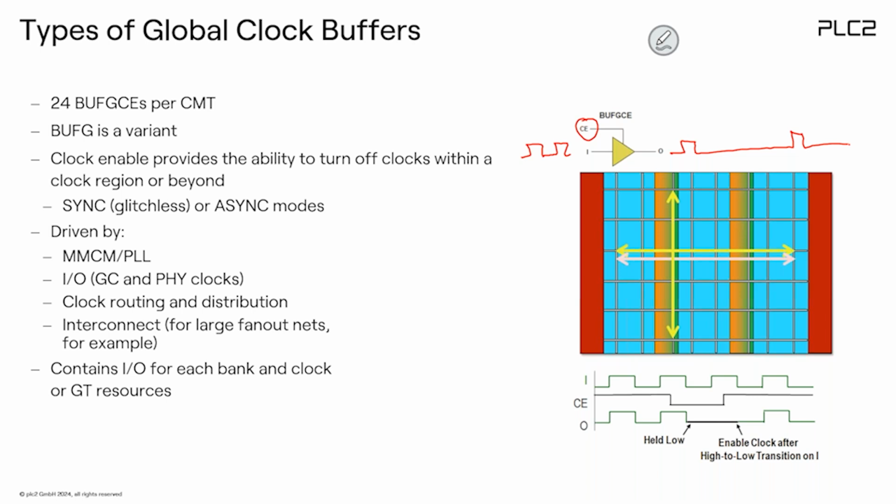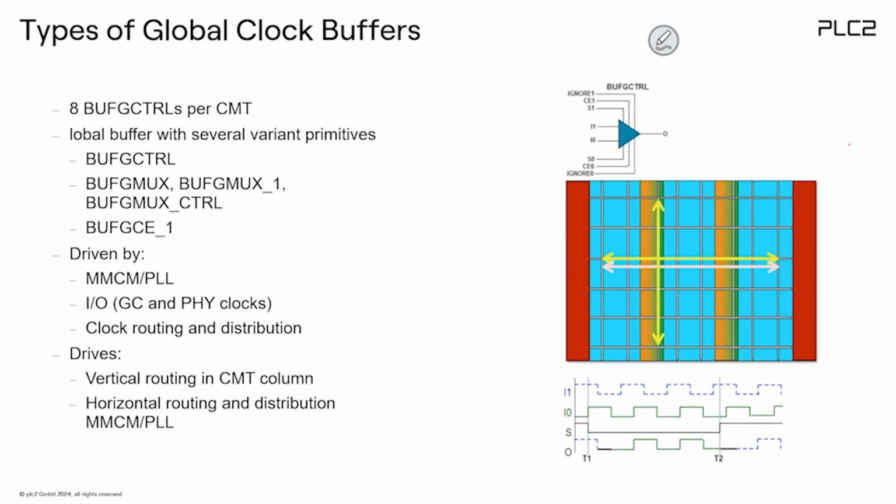But this is not done through a gate. This is done using a very, very special element, BUFGCTRL or BUFG control. That's a very, very flexible element. In this case, it's just a basic template. You can do a multiplexer. This means you can do something like this, so you have here a multiplexer with clock 1, clock 2, and a select.